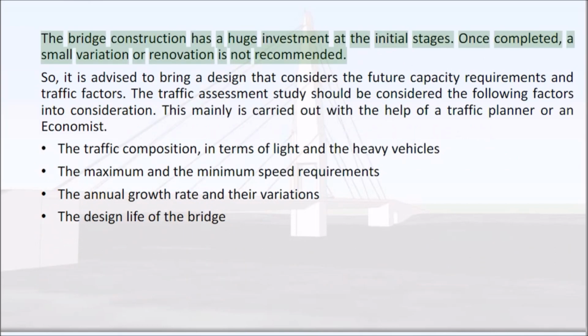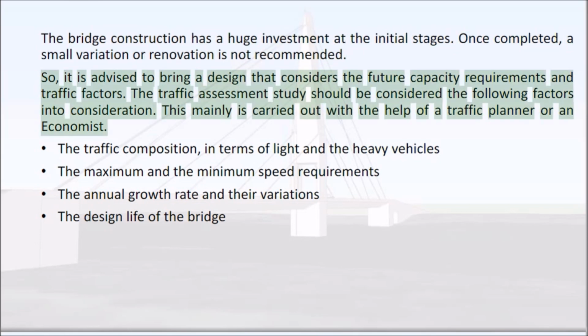The bridge construction has a huge investment at the initial stages. Once completed, a small variation or renovation is not recommended. So, it is advised to bring a design that considers the future capacity requirements and traffic factors. The traffic assessment study should take the following factors into consideration. This mainly is carried out with the help of a traffic planner or an economist.